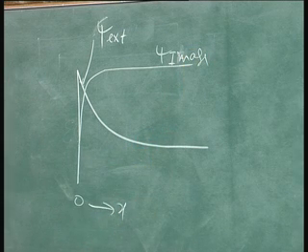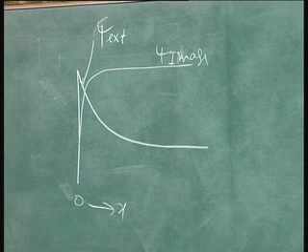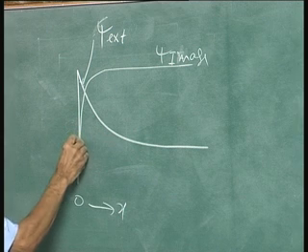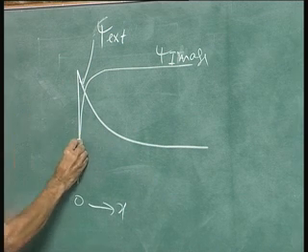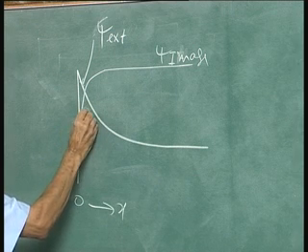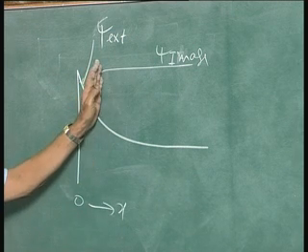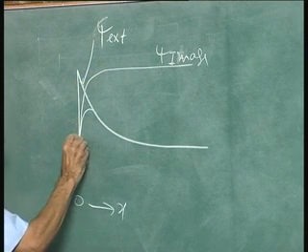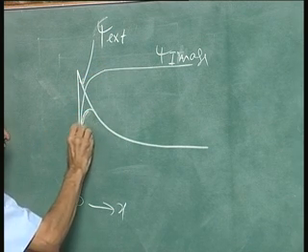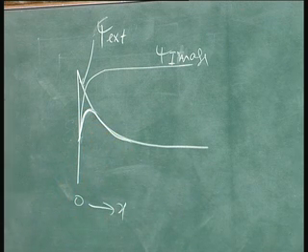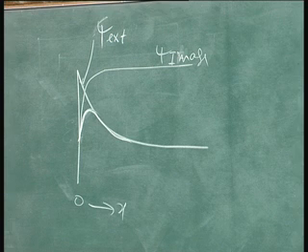So, the total potential variation, or the total band diagram variation, will be the sum of the two. Here it is very large compared to that. So, when you add these two quantities, it comes like this, and beyond that point it is 0, not varying. So the entire variation now comes up like this. That is what I plotted there. So, the total variation is like this.